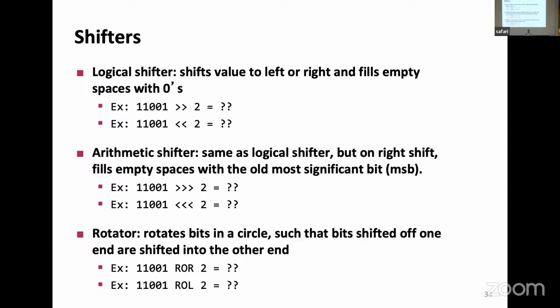Rotator, well, rotator is, remember the bits that I threw out? So I have the number, so there's 1 bit here, 1 bit here, 1 bit here, another one, another one. So if I say, hey, we are shifting this, it means that I'm pushing these bits. So the new bit is here. Logic, arithmetic, I filled it differently, okay. But there is this other bit that fell off. And in rotator, I take the bits that fell off and I insert them again on this side. Right? Boring? Okay.